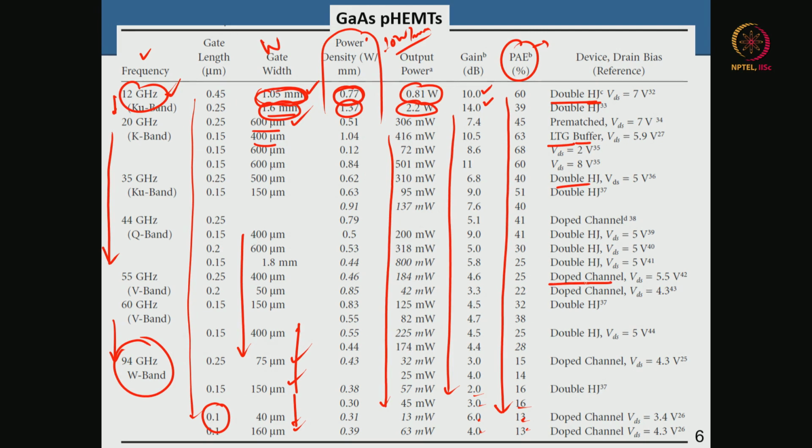Sometimes in the channel, in addition to having a 2D electron gas, people also put some mild n-type doping in the channel to improve the 2D electron gas even more, at the cost of slightly reduced mobility, because with doping in the channel you are defeating the purpose of modulation doping. So, your mobility will come down, but your channel concentration can be significantly high because there is already a 2DEG, although there is now doping. So, people can get higher current. So, similarly things, double heterojunction.